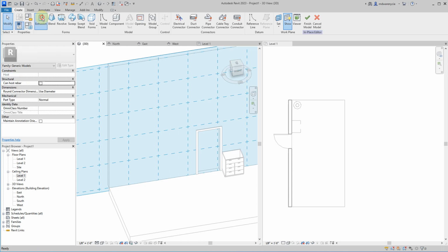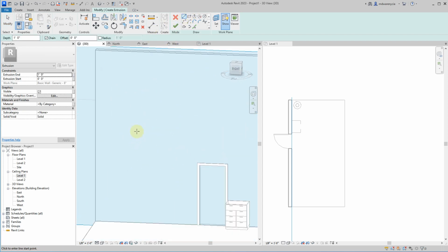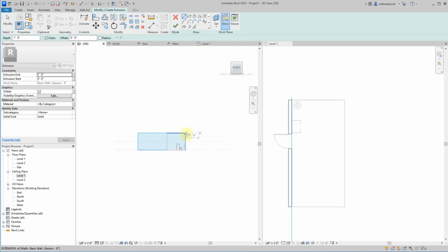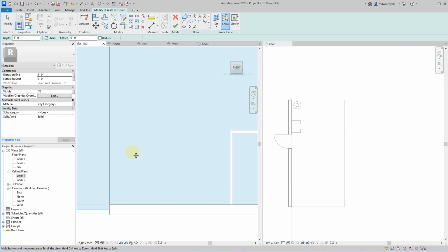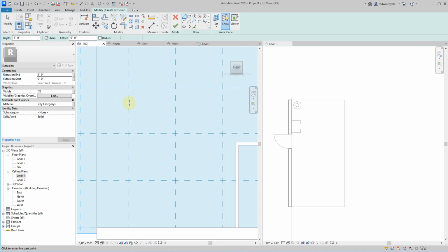So I'll start by doing an extrusion here, and you can see we've got some workspace. To make this a little easier on myself, I'm going to snap to this plane of view, because essentially we are working in a 2D space right now. Again, like how we were drawing floors and ceilings and how we can modify walls, this is working as a profile within Revit.